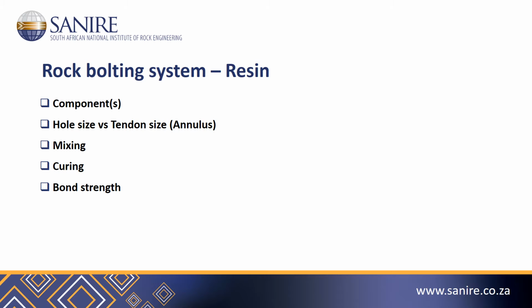And now the interaction, or the link, between the tendon which is installed into the rock mass. Talking about the resin, the resin consists of various components, and that needs to be installed the right way around into the hole. You have the components where you have the catalyst starting the reactions, and then the actual chemical reaction that supplies the glue, the contact between the two surfaces. The hole size versus the tendon size.